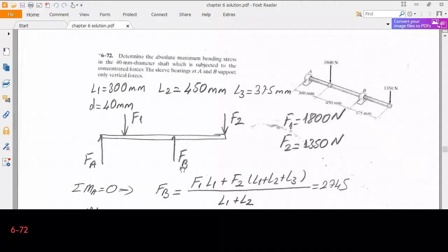In fact, we will write two equilibrium conditions. Sum of the forces and sum of the moments has to be equal to 0. In fact, it is better to calculate the moment with respect to point A. This will eliminate the contribution of point A since it will not generate any moment. Therefore, I can easily calculate the magnitude of the force Fb.